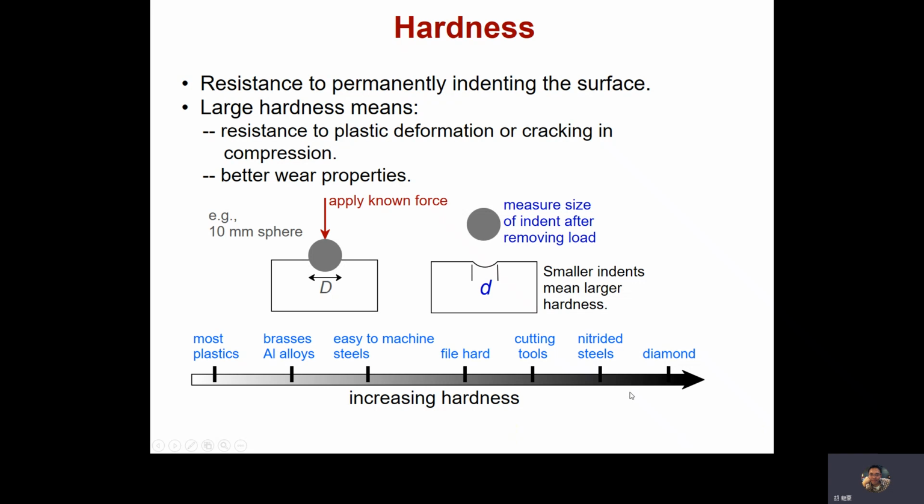How can you use a lower hardness cutter to machine a high hardness sample? It does not make sense. You need this concept of hardness. So you must know that an aluminum alloy must have a lower hardness compared to steel.